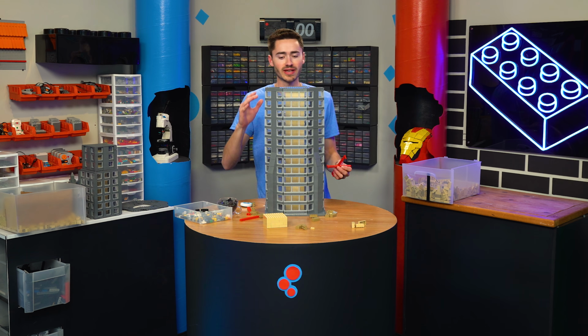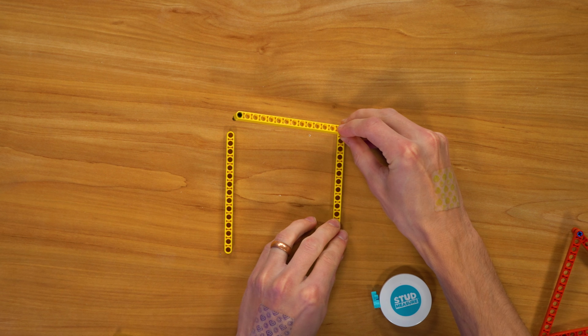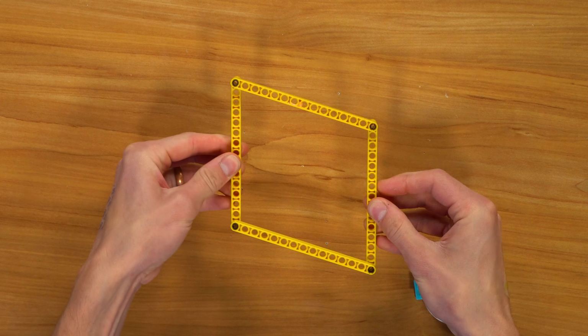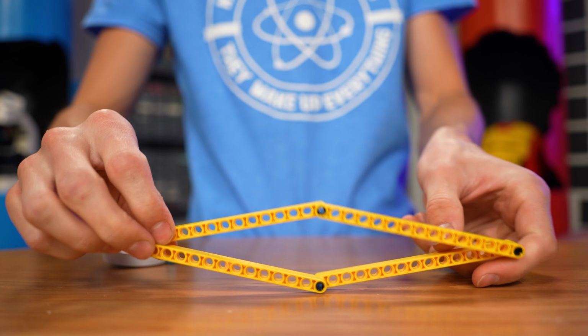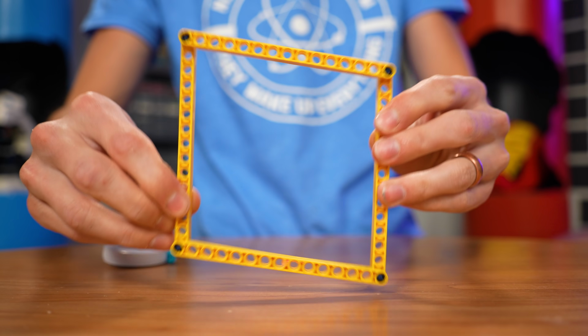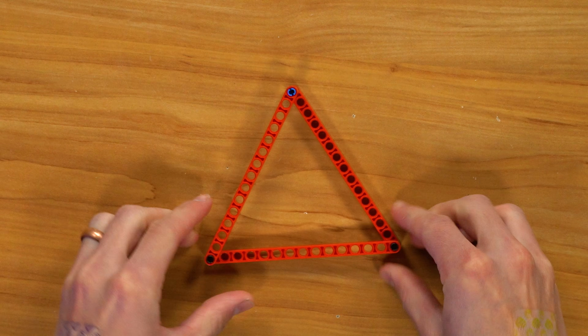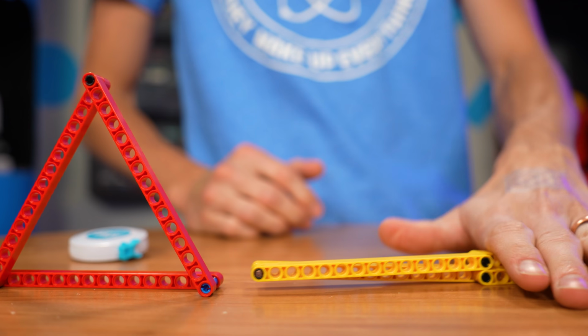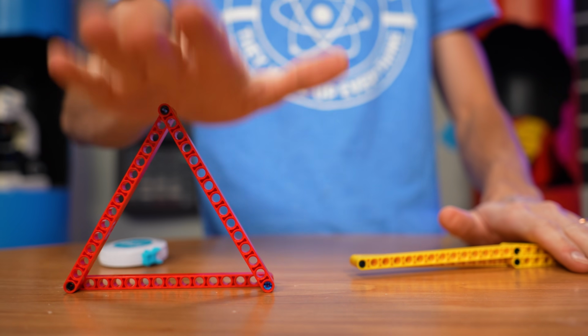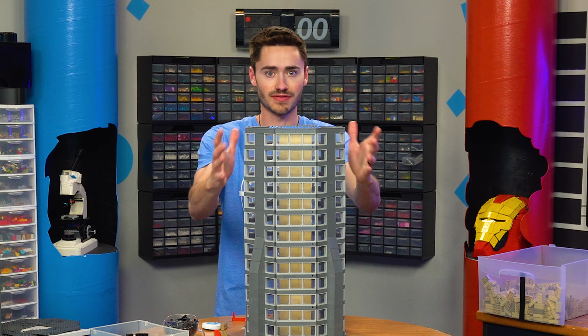And the reason we're gonna use triangles for this is it's a lot stronger. And you can see that if you create a linkage mechanism using 4 lift arms, when you press down on the top of it, it's actually extremely weak, because all the points where the lift arms attach to each other actually act as hinges. But if you take some of those same lift arms and create a triangle shape, where they're all linked into each other, none of the connections are able to hinge, creating an extremely strong shape when you press down on it. And that's the same thing we're gonna do on the base of this skyscraper.